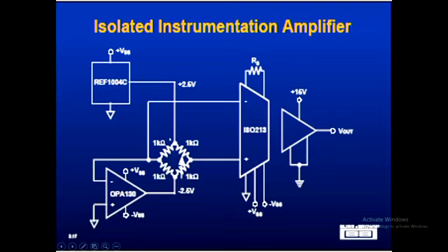So there'll be a current flowing through this upper 1K resistor. Where does it go? Well, it doesn't go there because this doesn't draw current. It doesn't go there because this doesn't draw current. It's got to go through this resistor down here. And it'll be the same current flowing down that way. What will the value be? Good. Okay. So we've got 2.5 milliamps flowing down here. Doesn't go that way, doesn't go that way, it's got to go that way.